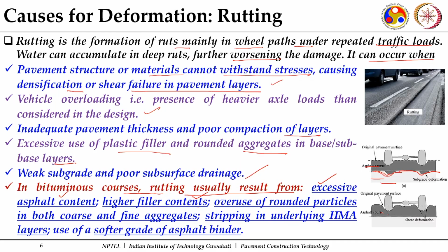And there are particular sizes: fillers which are less than 10 micron can act as a part of binder extender also. So this is another concern. The filler contents have to be properly controlled, because the fines collected in the hot mix plant through your secondary collectors, when they are reintroduced, the content of these fillers needs to be properly ensured so that they do not exceed the designed limit.